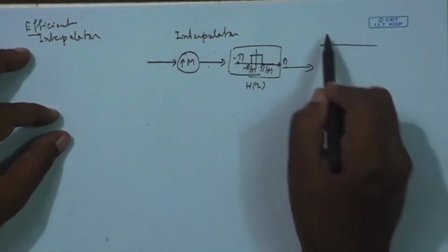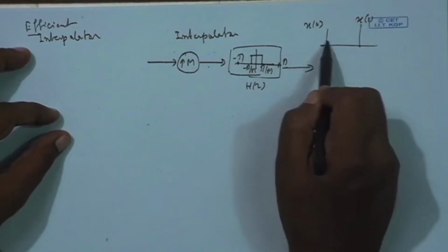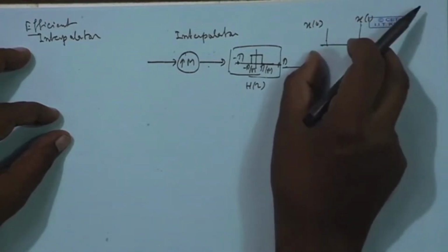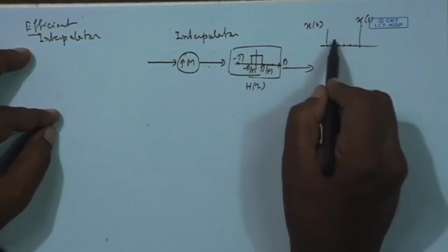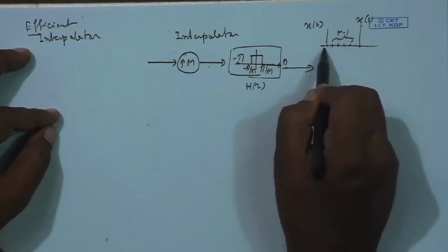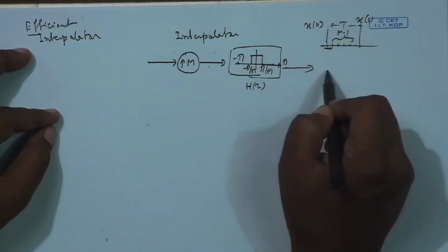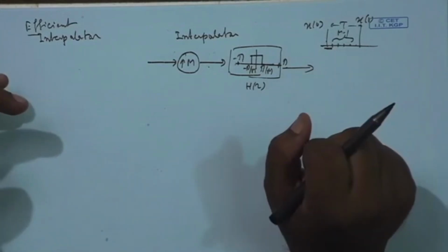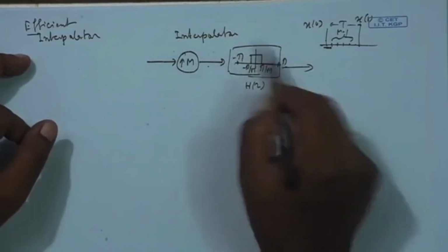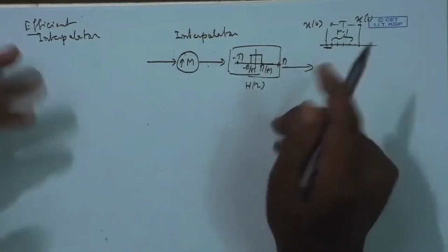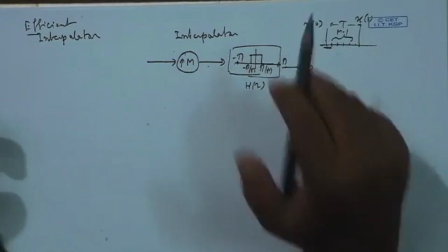That is, I am creating between, say, x 0 and x 1, where earlier the sampling period was large and so the sampling rate was small. Now I am bringing in intermediate sampling points, a total of m minus 1 zeros. So now the sampling period is tau, and if the total is T, tau is T by m. So the sampling period is going down, which means the sampling clock here is m times faster. So the filter is working at a faster clock, m times faster, which means it is costly. How to bring down the cost, how to make it operate at a lower rate?